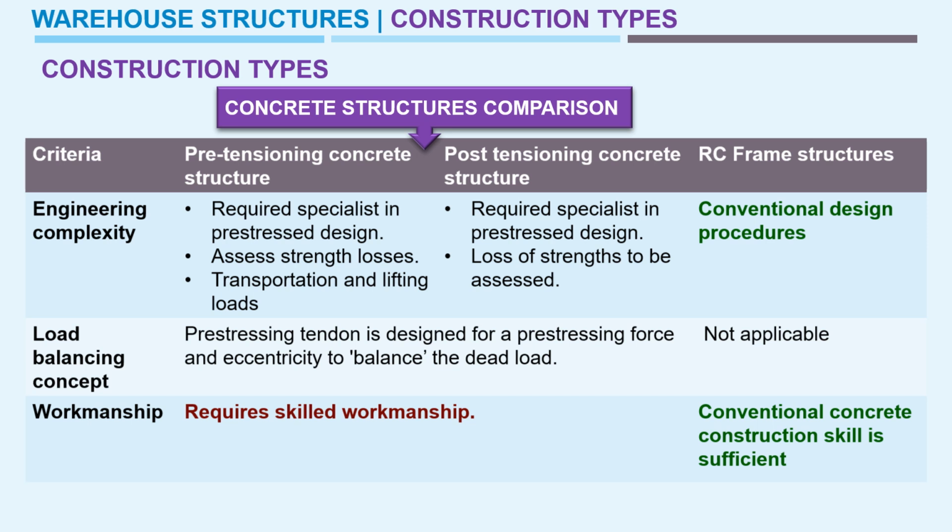So for a continuous beam, we can do load balancing analysis, so that only where the actual load is going to occur, for that section, we can provide a deeper or optimum section. Accordingly, balanced load transfer is possible with pre-stressed concrete, that is pre-tensioning and post-tensioning, but it is not applicable for RC frame structures, because in RC frame structures we need to provide uniform beam sections, and the required depth does not depend upon the loads.